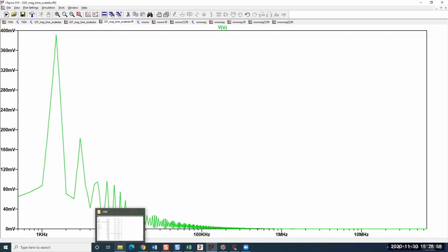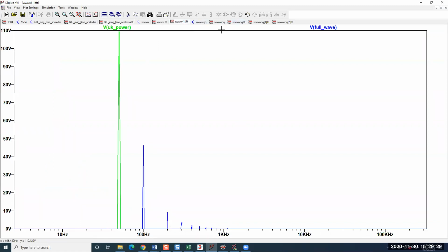Now, something you might not know is that a way to test a multiplier is to actually have it square a sine wave, right? And then look at the FFT, right? And a squared sine wave does have a pure signal at twice the frequency. And if you're seeing things beyond twice the frequency, well, those are nonlinearities. I just pointed this out because that kind of question was on an exam recently.